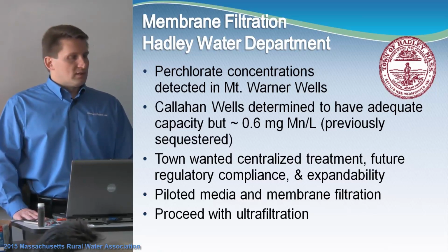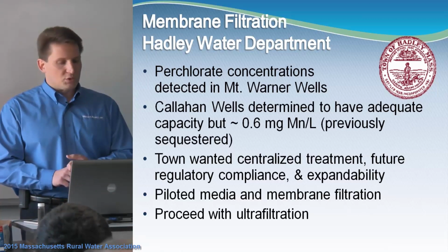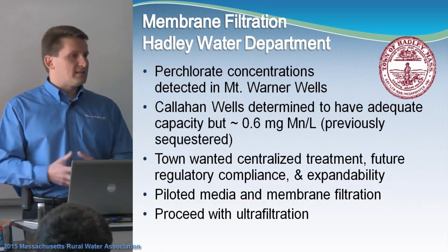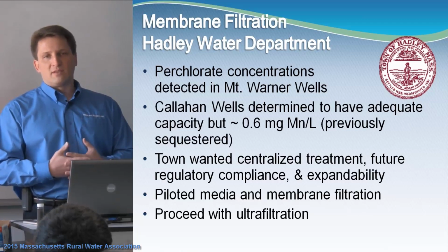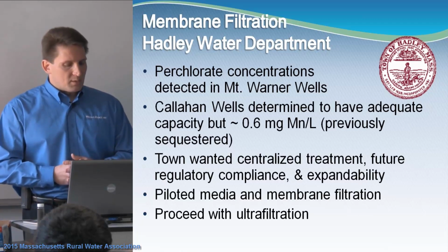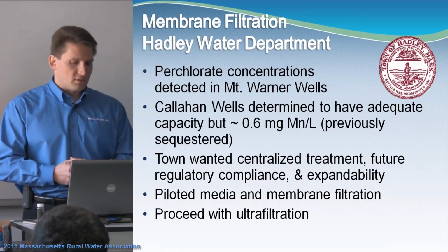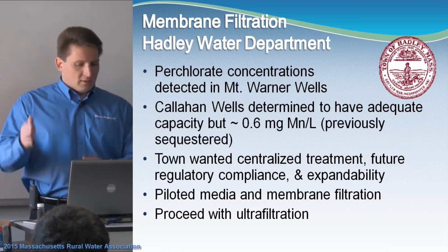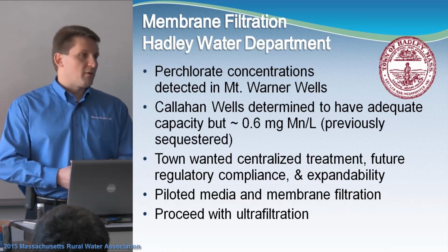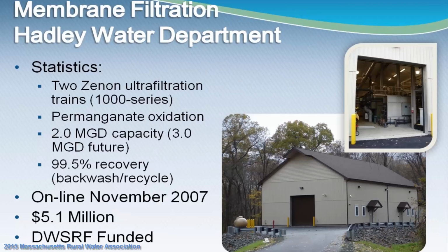One of the goals that the town wanted was to have a centralized treatment facility for the entire town, which had future regulatory compliance, not just for that contaminant, but also for what could be anticipated in the future, as well as expandability for the town as it grew. So what we did is we piloted the green sand medias to bracket the cost-effective pressure filters, and also membrane filtration, because that's something that they were very, very interested in. And ultimately, through piloting, ultrafiltration worked very well, and based on their desires, that was the one selected to proceed with. Two Xenon ultrafiltration trains, the 1000 series membrane.